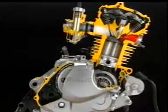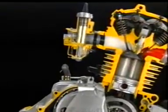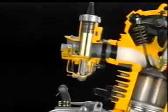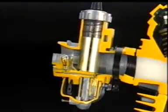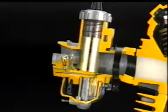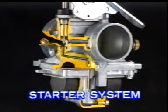When the engine is just being started and has not yet warmed up, it needs a richer mixture with less air in it. There has to be a way to bleed the air out and supply a richer mixture to the engine. This is done by the starter operation system, which temporarily increases the amount of fuel when the engine is started and shuts off the flow of air to make the fuel-air mixture richer.